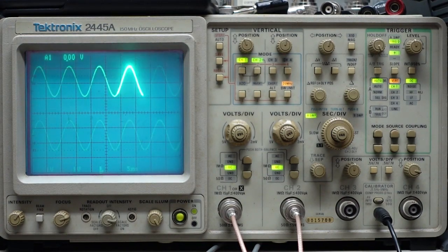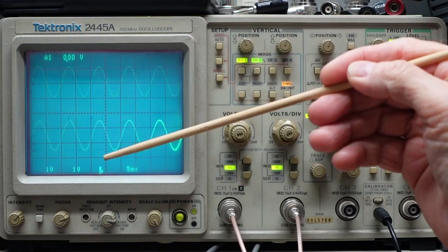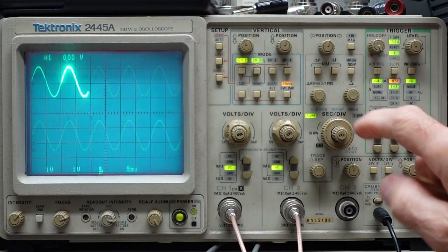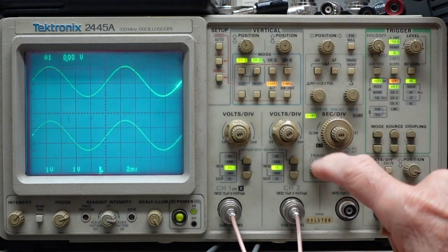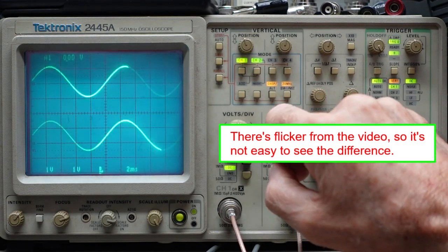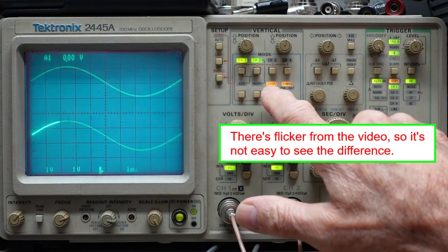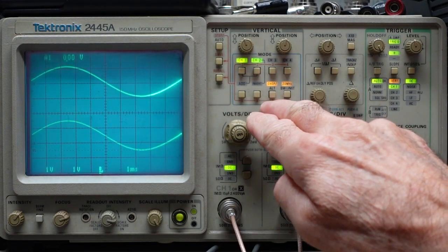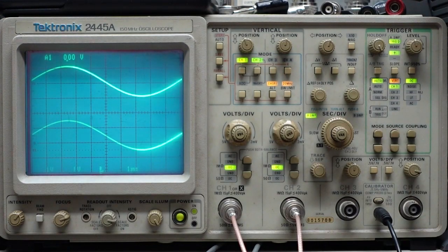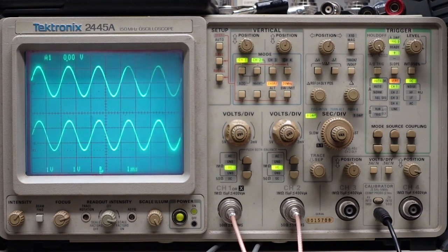Okay, but chop mode doesn't give us alternate sweep. It chops rapidly between both and helps to eliminate flicker. So when I go from alternate sweep to chop, our flicker drops dramatically. That is the function of the chop and alternate sweep buttons. I had no idea what this is for when I first started out, but it makes a lot of sense. Somebody took the time to explain it to me. Had they not, I might have found it in the manual, and I might not have.